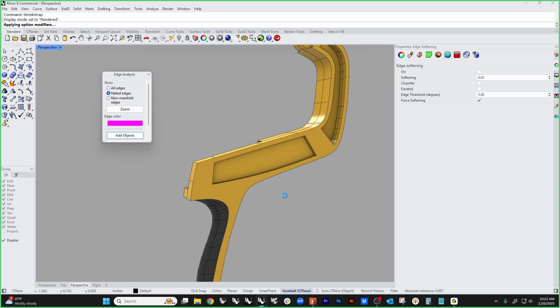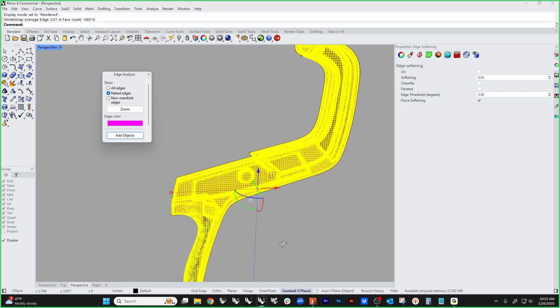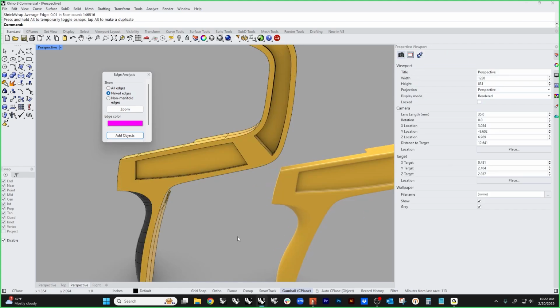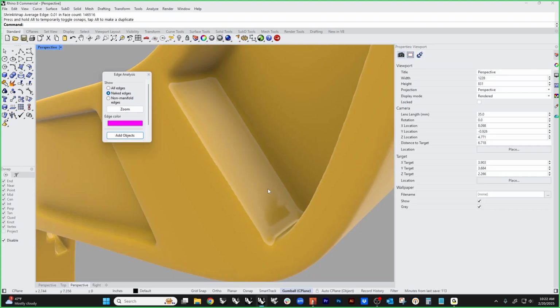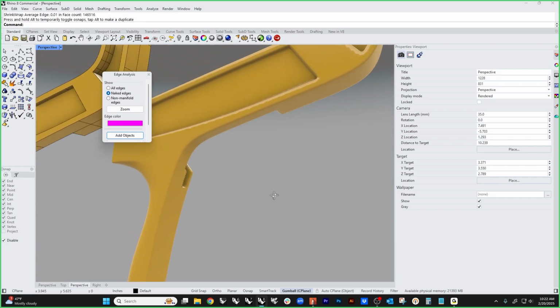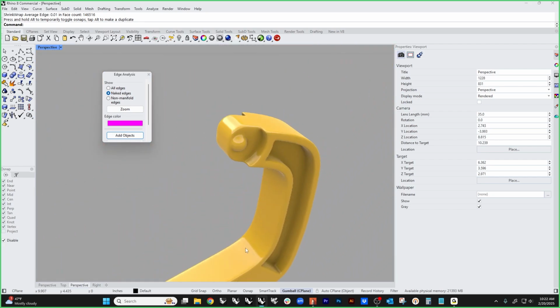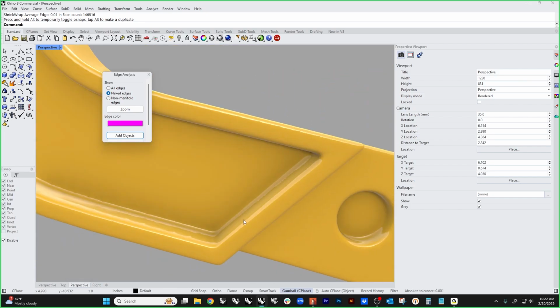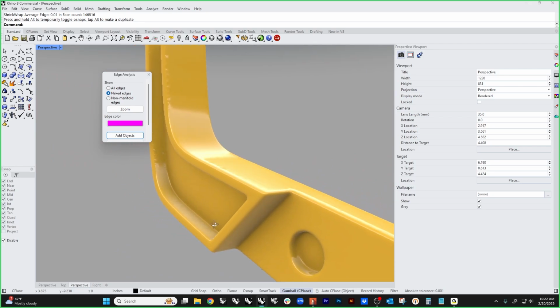Instead of a bump map for this grip, you can apply a displacement, which displaces the render mesh. You can extract the render mesh without softening and then shrink wrap the render mesh and end up getting a beautiful soft part that has beautiful soft edges like this. And this will print absolutely wonderfully. So shrink wrap is a really cool trick if you just need an overall softness. See that?